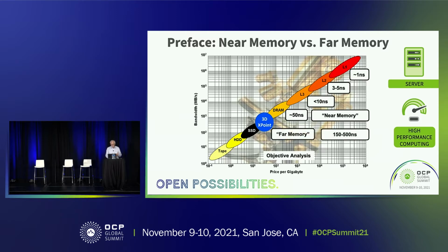There's currently a lot of interest in adding even more DRAM and perhaps 3D XPoint or Optane memory and other technologies in the memory pools via any of a number of interfaces, which include, for instance, SMP, OpenCAPI, CXL, CCIX, Gen-Z, and even PCIe and Ethernet. These we will call far memory. They're a higher latency memory.